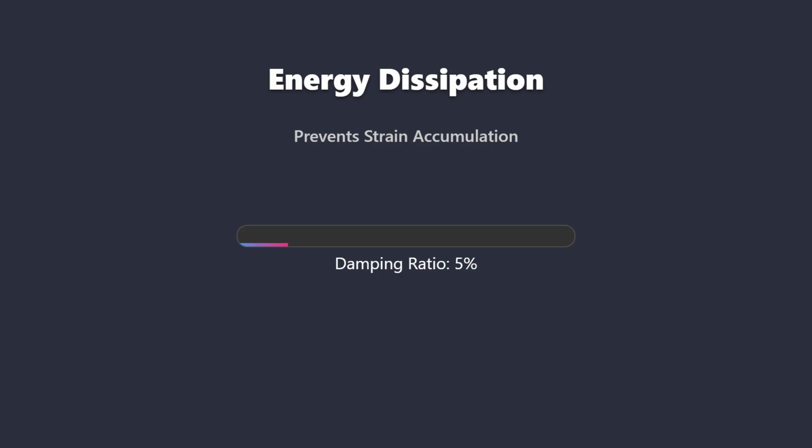This absorption prevents the energy from accumulating as damaging strain energy within the primary structural members. The primary function of dampers is to significantly increase the effective damping ratio of the structure. Conventional structures typically exhibit a damping ratio between 2 and 5%. Damped systems elevate this ratio substantially, often reaching 15 to 30%.